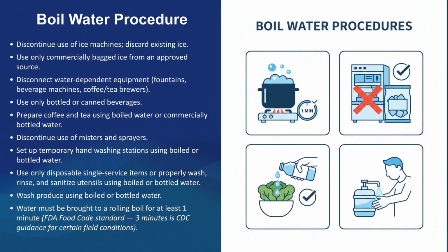In a boil water procedure, discontinue the use of ice machines and discard existing ice. Use only commercially bagged ice, bottled or canned beverages. Prepare coffee and tea with boiled or commercially bottled water. Water must reach a rolling boil for at least 1 minute.